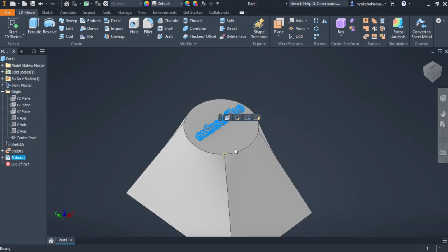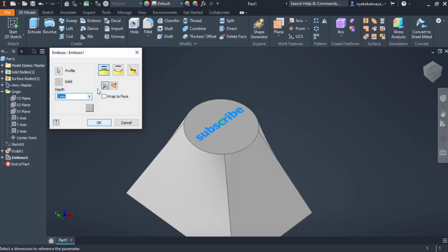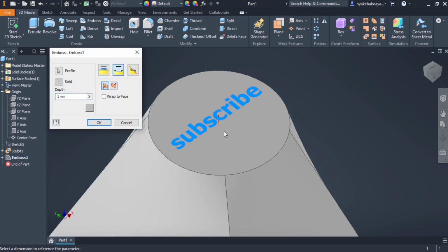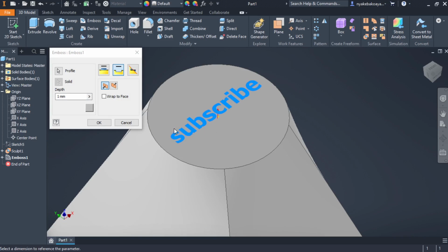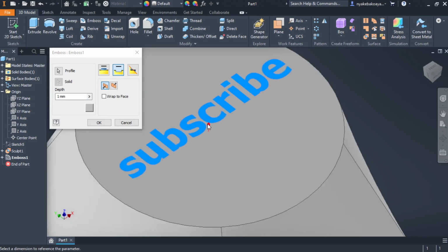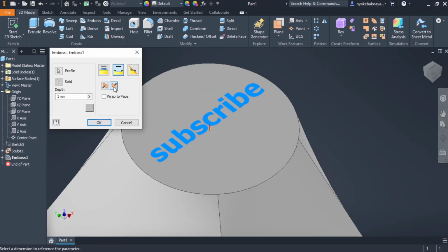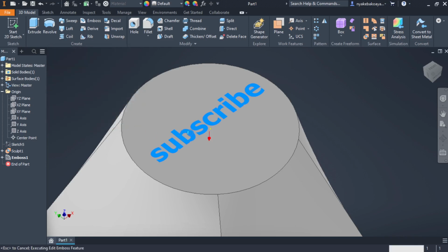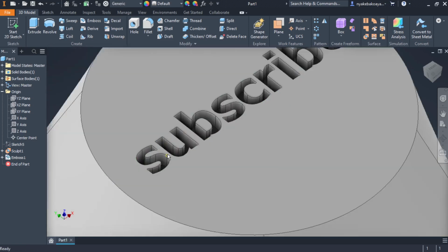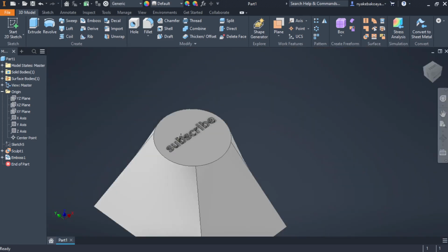All right, I want to show you the other one. We can edit this. We can do a subtraction. Now for subtracting, it's like you are removing material, and you can see this arrow projects upwards. We want to shift that to the bottom such that it subtracts. Click OK, and then you can see what it does there.